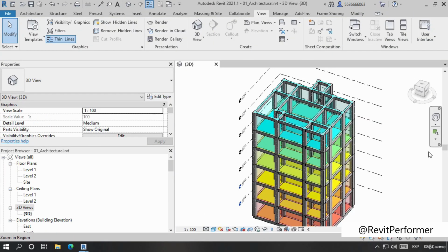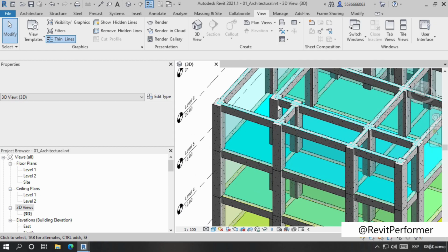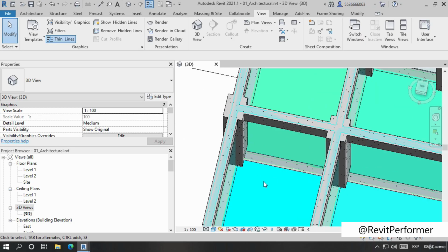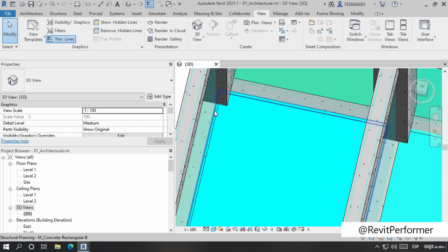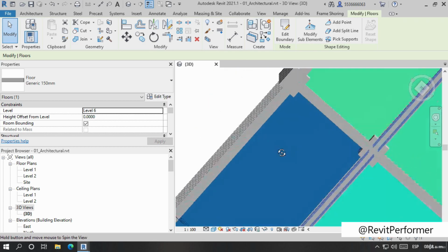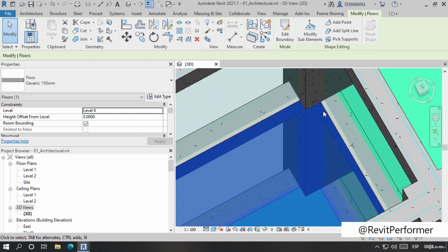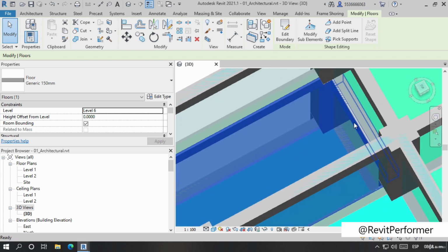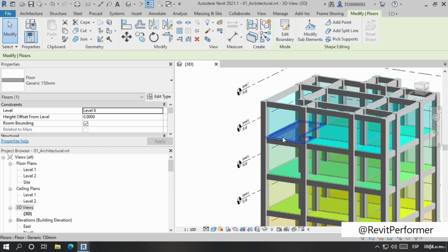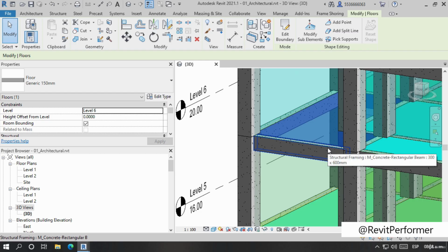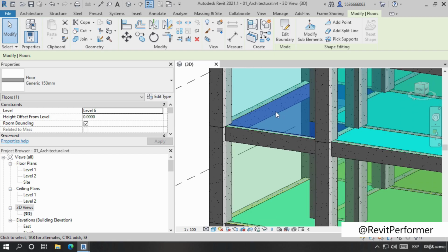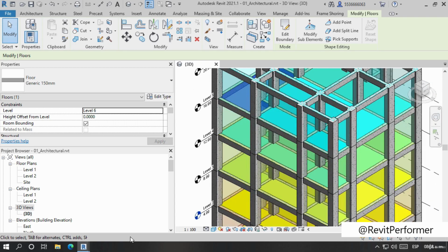So our next step will be to create the structural floors. We already have a reference because there are some floors being created, so they give us the idea of where they need to be placed. But remember that these floors have been placed through the wall settings. So we actually need that these lines are inside of the axis, so that if the floor is created, it's already used within the same elements. If we're using different type of structural methods, we also need to get the framings a little lower, and then the floor going up, getting the subtraction of the column. So let's see how that process needs to go.